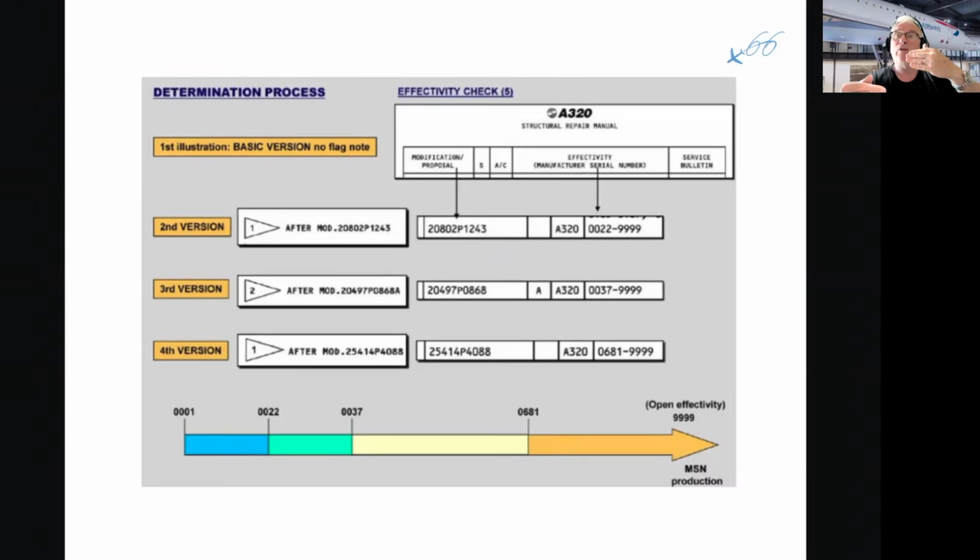So not only do you have to locate the damage on that particular skin, depending on the aircraft, MSN, the weight variant, and all the other additional effectivity and all that, you have to find the right part number of the skin for that MSN aircraft before you can start assessing any damage, because the inside of it will have different milled out areas depending on its production and its status.